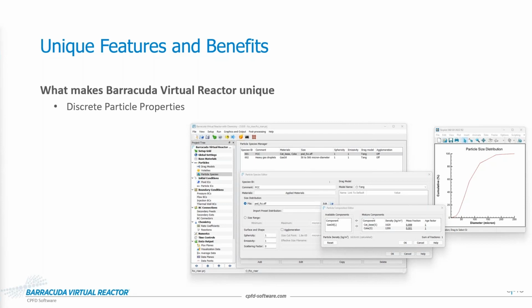And the first here is discrete particle properties. This is something that's really important to fluid particle systems, to fluidization. It's not just the particle size that matters. It's also the distribution. Fines content can take a fluidized bed from a turbulent well-mixed mode to a gas streaming mode due to lack of fines.